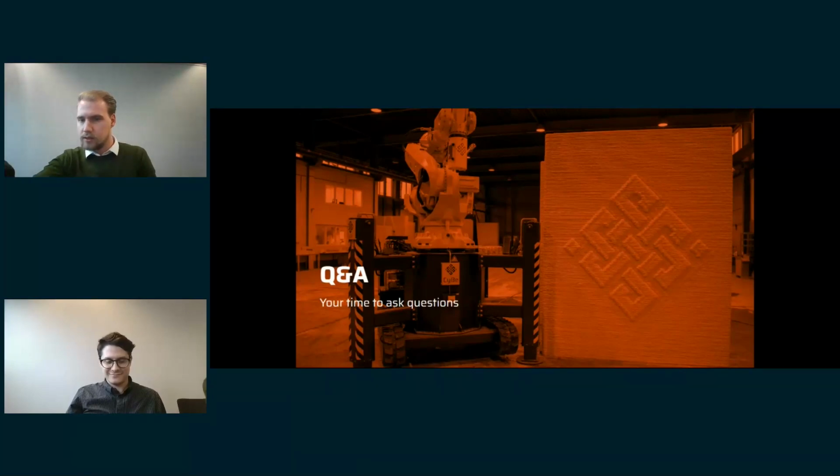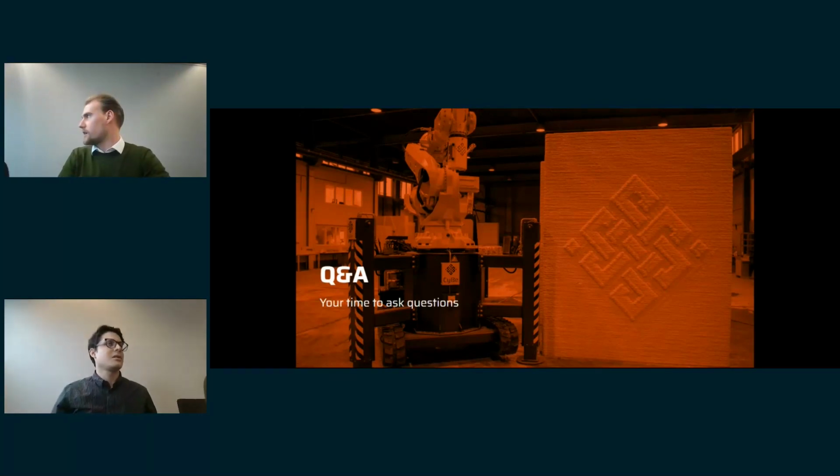What else do you check? We test local materials. At the moment, the first step is to send the sieve analysis, and then we go further. After we check the analysis, probably the size of the aggregate, and probably after that the roughness as well. But that's something for a later stage. For the first part, just this.